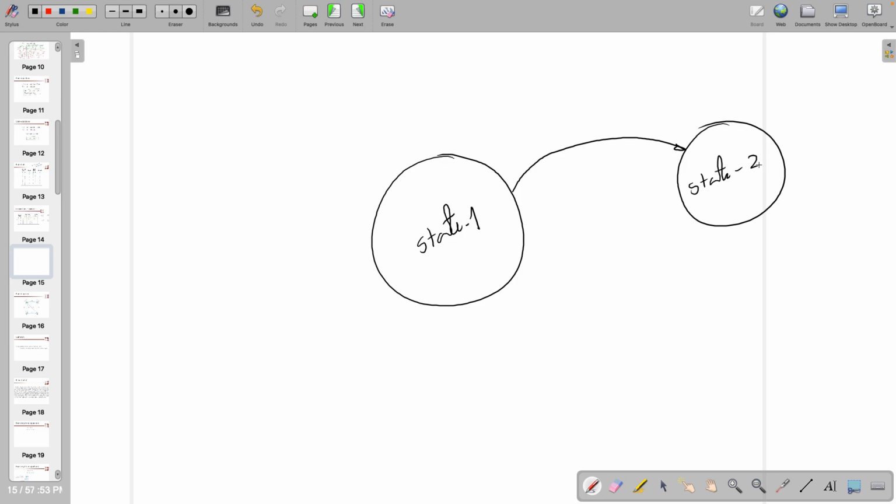state 1 to state 2 will be there if there is a certain input I am applying, and whatever the output will be, I am going to write down with an oblique. This is the notation. Between 2 states there is a transition when input is whatever value we write here, with whatever value we write here as output.